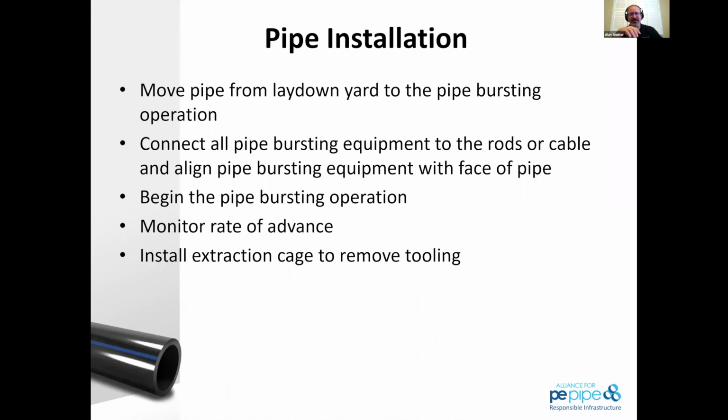High density polyethylene allows a 10% gouge, and most of the scrapes that you get while pulling it over the surface of the road are well below that 10% gouge. We want to make sure when we are pulling it into place in the field that we do not pull it against something that has a protrusion or could gouge that pipe well beyond that.